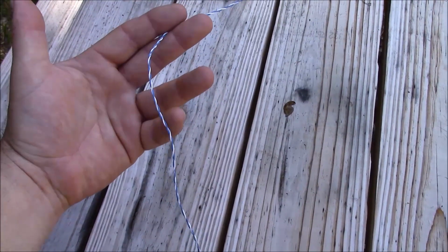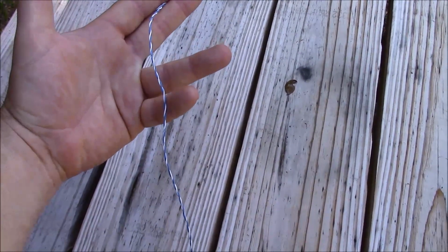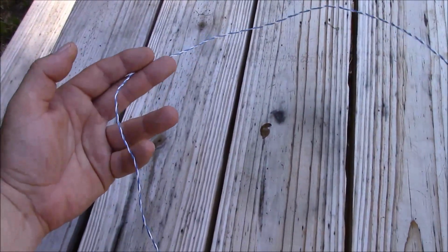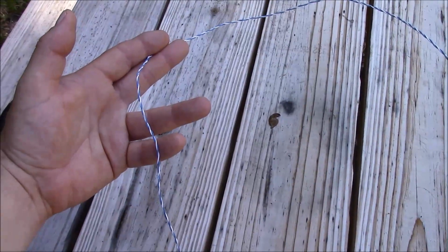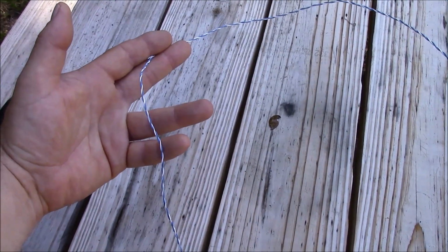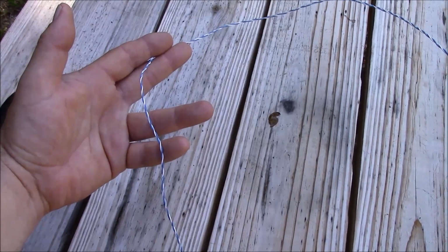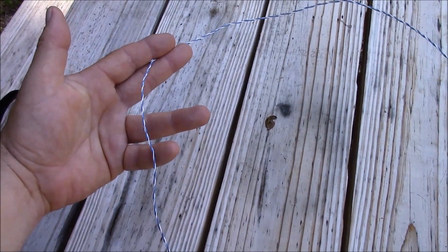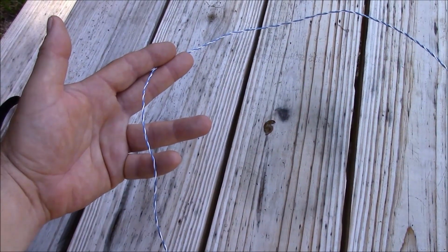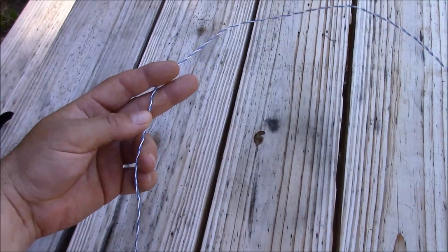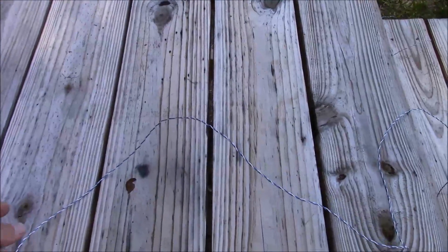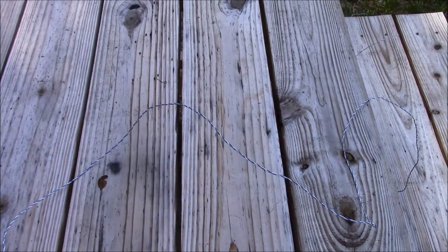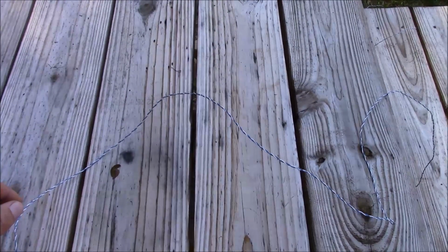So what we've seen from our testing is that Cat 5 twisted pair will work as an RF feed line if it had to be pressed into service as such. Now I wouldn't recommend running a lot of power through it, however. We saw that it did tolerate the power of a mobile radio, but I don't believe that it would tolerate it for a prolonged period of time. I think that keeping your power level around HT levels, it would work just fine. Would I replace coax cable with Cat 5 twisted pair? Absolutely not. But again, if you had to press this in service, I think you'd be good to go.